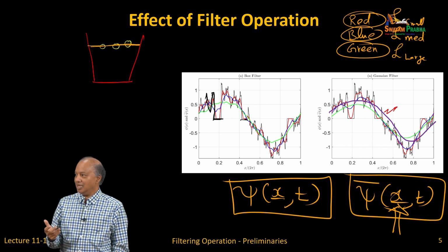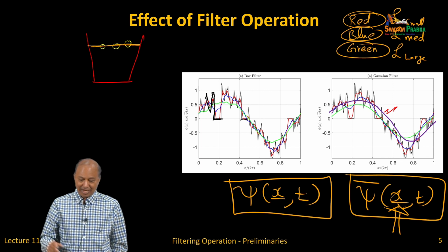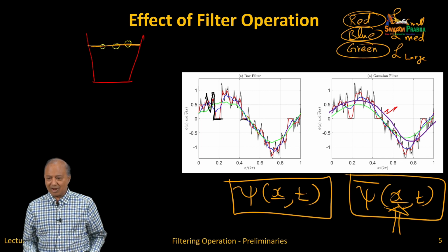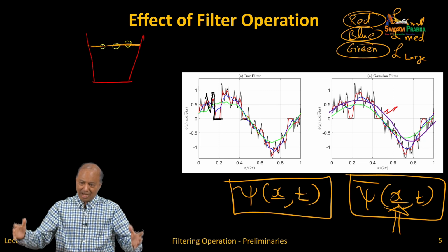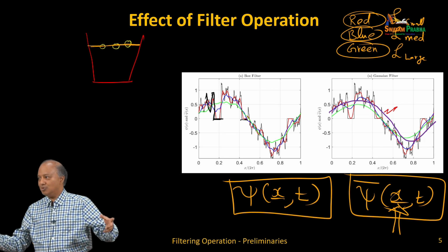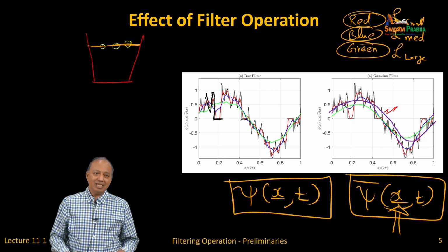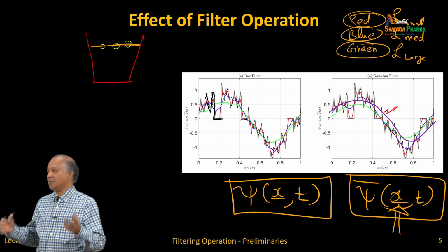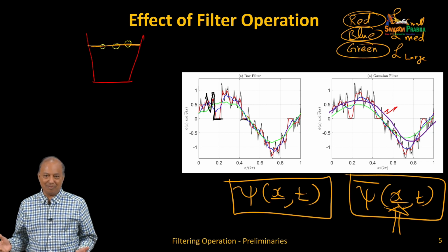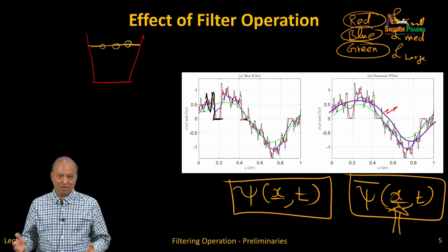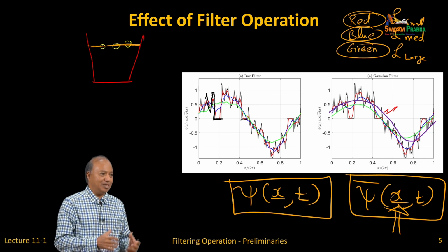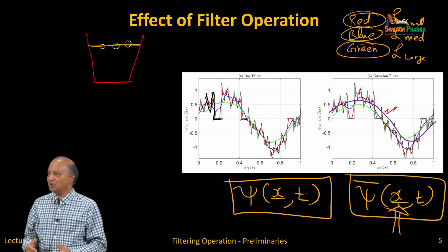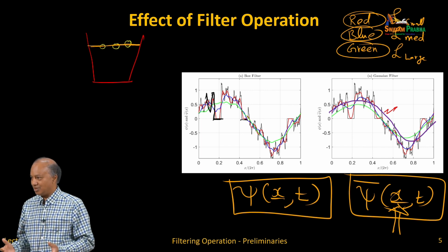Okay? But in the next few slides, I said, okay, take the Navier-Stokes equation and you do the filtering. Instead of filtering, every time I use the word filtering, you can replace it by ensemble average. And you get the same thing. So in other words, lots of models that we need to do for LES, you will have to do in RANS as well.